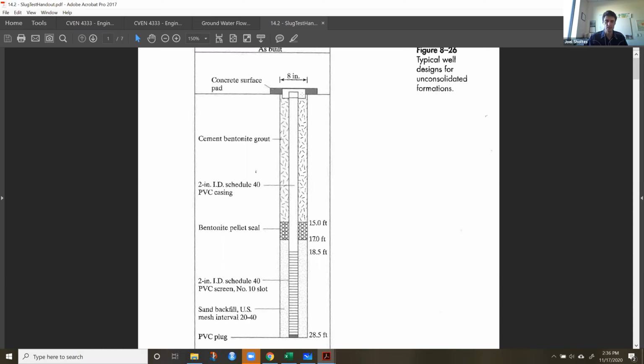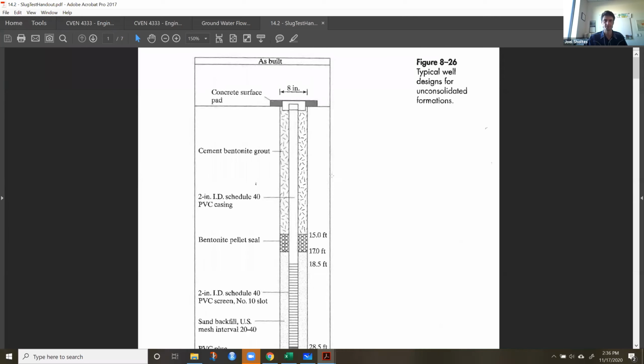If a pump is put into a well, there's a couple ways to do it. You can put a well in and just kind of create suction and lift it all the way up, or you can put a pump in on a tube, and the pump goes all the way to the bottom where the water is. The pump goes down here, and the power source goes down here, and then it pumps up a tube out into wherever you use it, into your supply line.